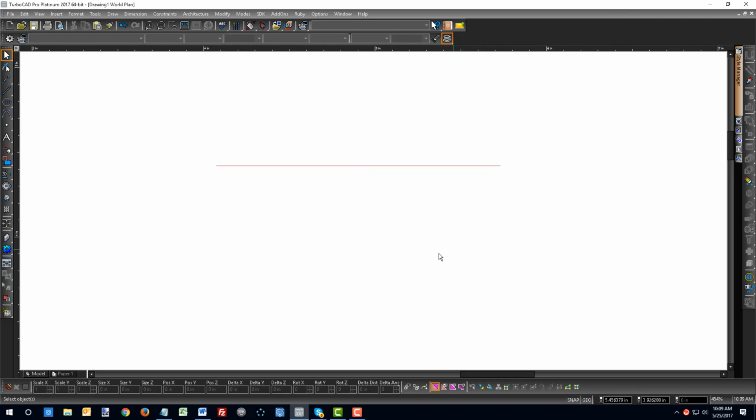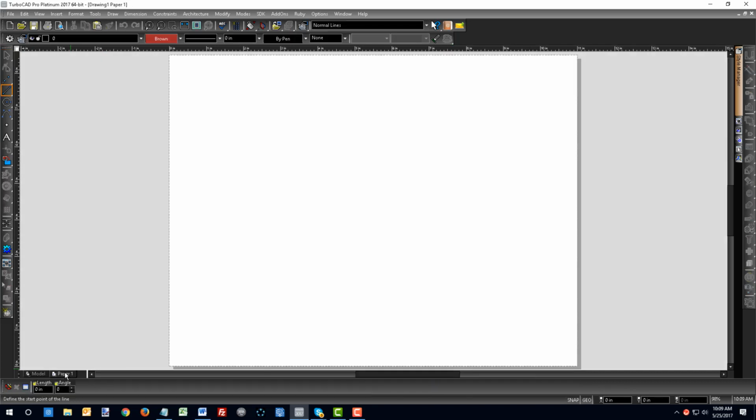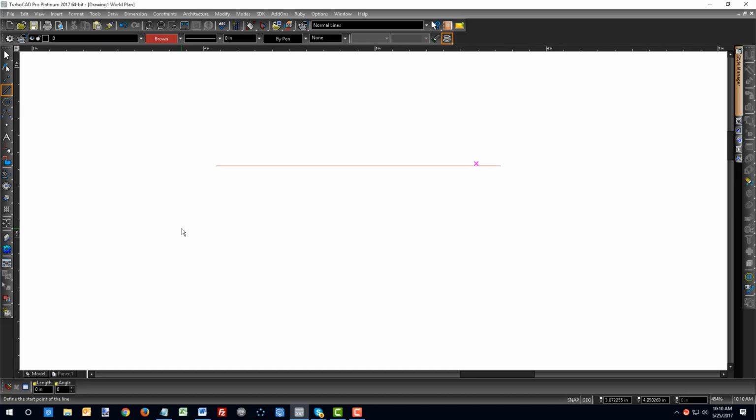And this is because you've got to actually have an object in your drawing to make use of these. The drawing area itself is by default set up to allow you to draw in model space. We recommend you draw in model space at a 1:1 scale. And then we've got a tab down here called Paper Space. The Paper Space tab allows you to create layouts and insert viewports so that when you need to scale your drawing contents, you can automatically do that through our viewports and not worry about having to scale from the beginning of your drawing session.